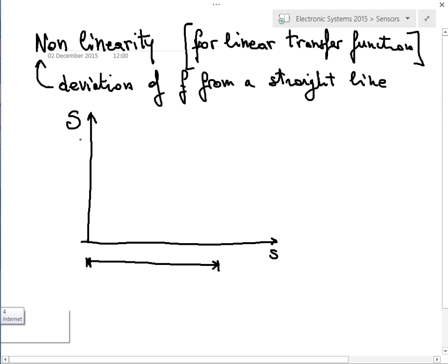You can imagine the situation before, the voltage as a function of temperature and so on. Let's assume this is the span. In the case of a linear sensor, after calibration, one has this part without error and typically the other extreme without error, so that the nominal transfer function is linear.